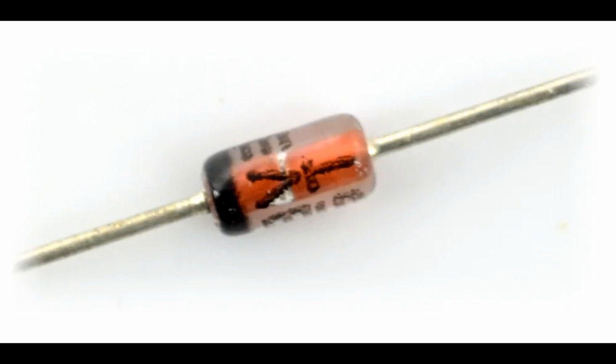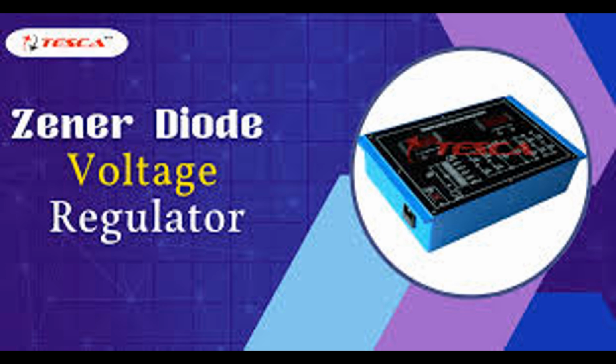7. Reverse-biased Zener diodes. Description: these are regular diodes operated in reverse bias mode at a voltage higher than the breakdown voltage, typically used in avalanche mode. Characteristics: higher Zener voltage range, typically above 5 V, where avalanche breakdown is dominant. Suitable for high voltage regulation and protection. Applications: high voltage power supplies and surge protection circuits.